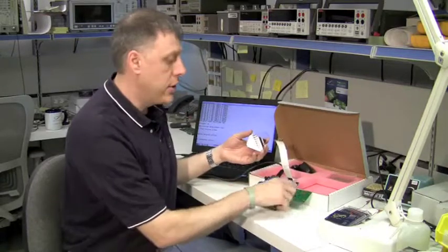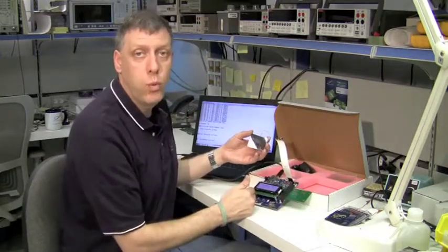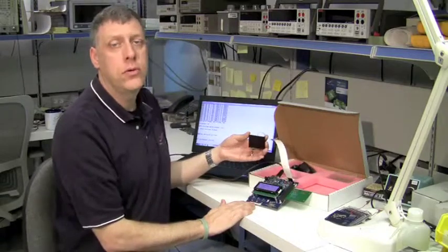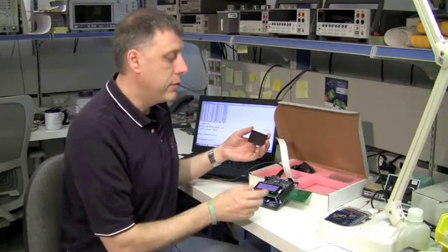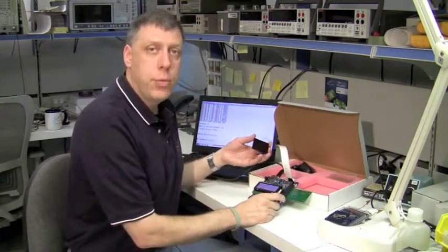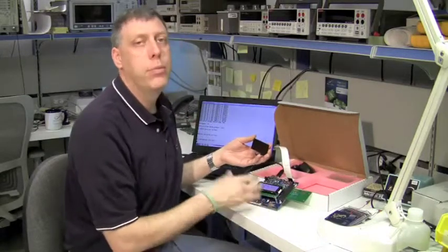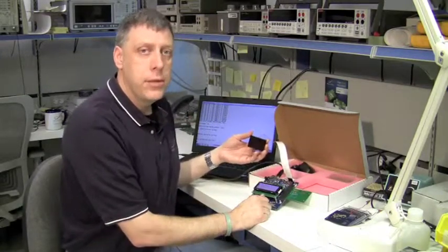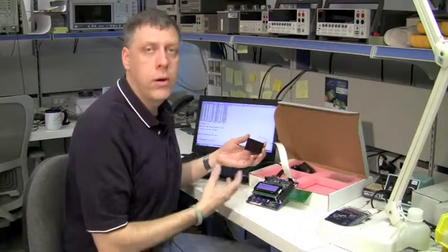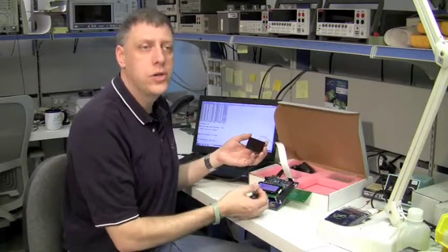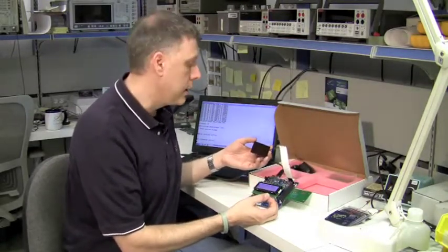So there is some protection there for the MEC, and that's another reason why you want to use the ADP kit when you're developing your products, is because if you were to just put the MEC on your product without first debugging it, you would probably end up initially damaging the battery if you have a short or other problem on your board or your charge system isn't working correctly.